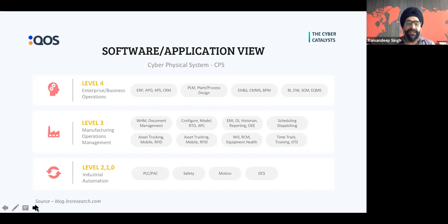Then we have level 3 devices or information systems. These are basically the information processing units, which actually bring in the human interaction with these machines, these programmable logic controllers. So that's what actually sits in level 3. And then comes the analytics, like SAP or ERP or smart warehousing. All those systems will come in level 4. You can further read that, because of the inclusion of cybersecurity, now you would see something in the decimal also being talked about, like level 2.5 or level 3.5.